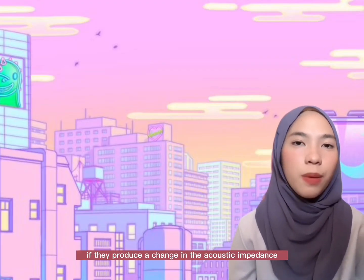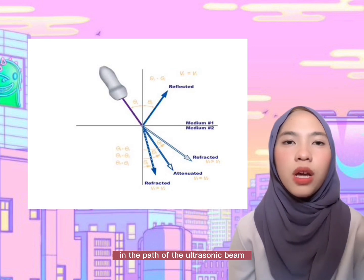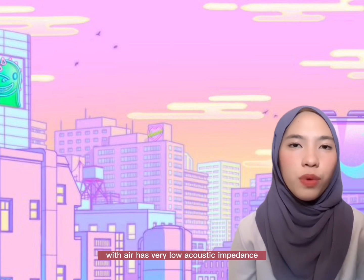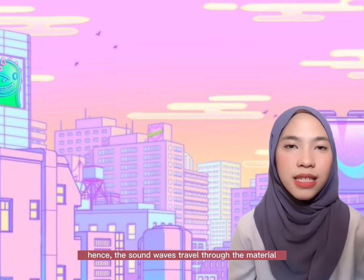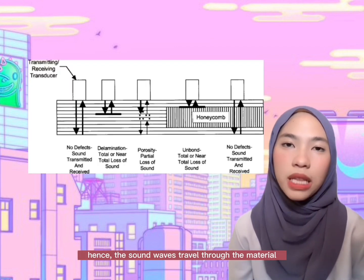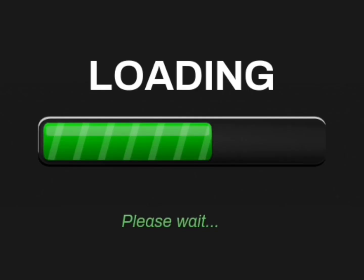Defects are detected if they produce a change in the acoustic impedance in the path of the ultrasonic beam. An open crack filled with air has very low acoustic impedance, so it will reflect virtually all the acoustic energy incident on it. Hence, the sound will travel through the material and be reflected back from the crack or flaw.